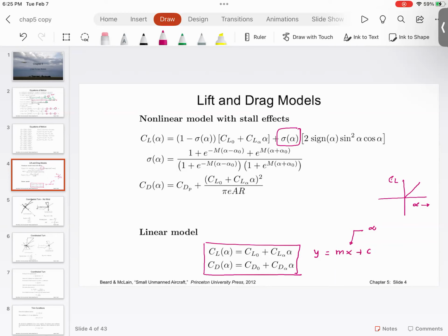For quadcopter, trimming means the quadcopter is able to hold its altitude, or quadcopter is able to hold its position, not rotate about the yaw axis. That is why the trimming is done in quadcopters. But in the context of the aircraft, we want the aircraft to continue to be in steady flight.